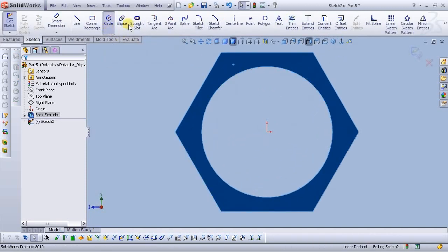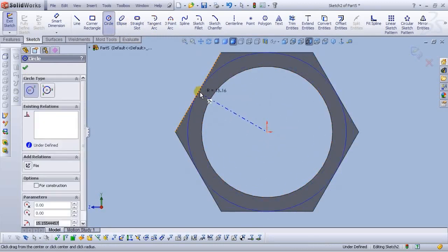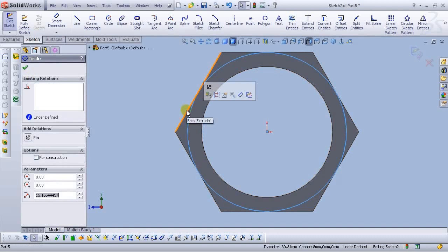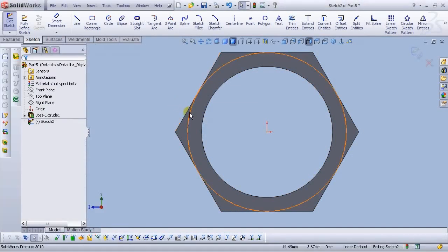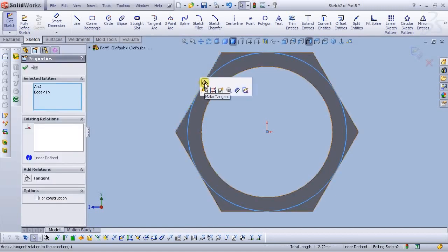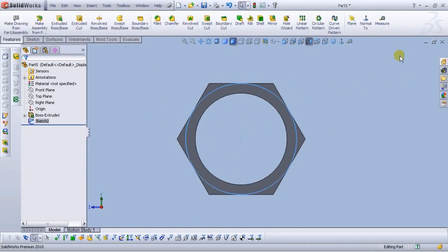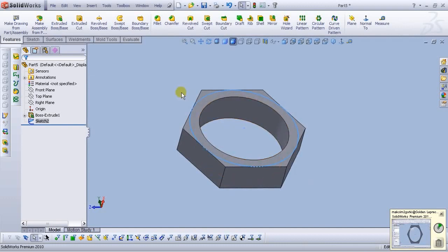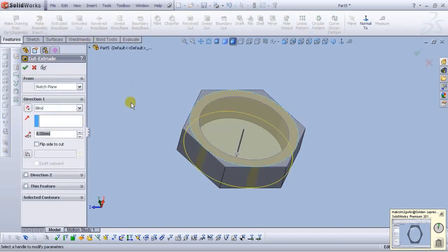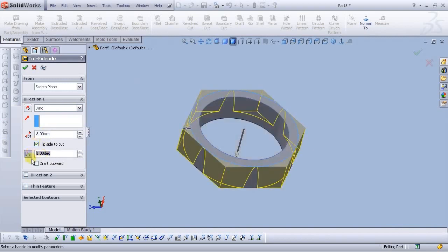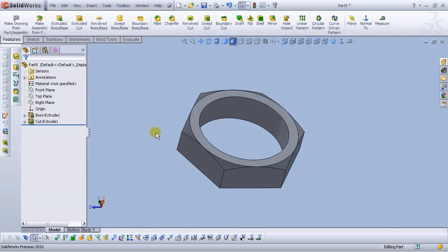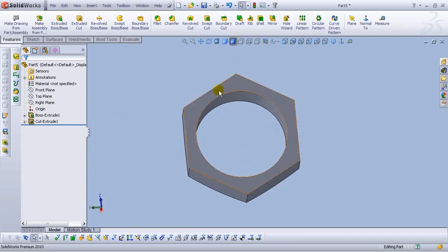Now we're gonna draw a lock nut. Go to right plane and open sketch. Select a polygon. Okay. Let's smart dimension. Let's delete. Before that, let's make it horizontal, this point and this point. Okay. Now let's smart dimension from this point to this point and type 35 millimeters.